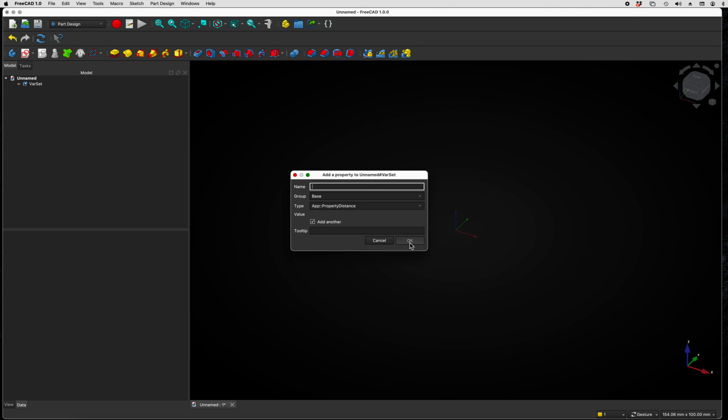We're going to now add body thread height, which is, like I said, the distance above the top of the body, which is the height of the threads. Body thread height, tab, tab, tab. And we're going to set this value for now for 5 millimeters. It doesn't have to be, but it could be whatever you want it to be.